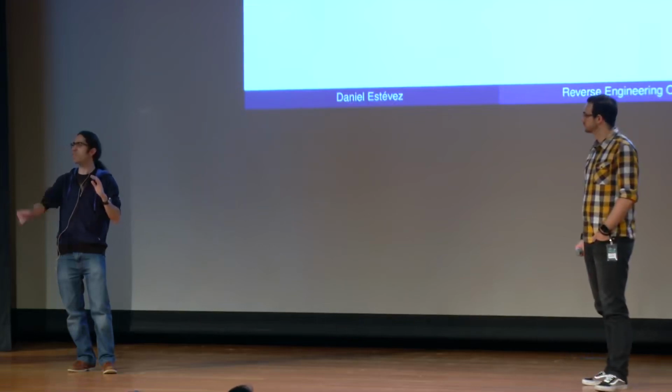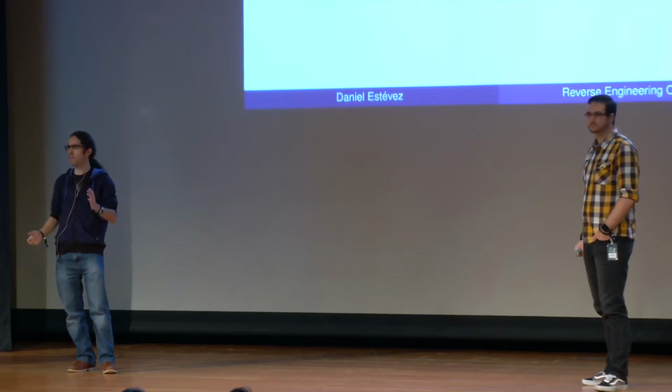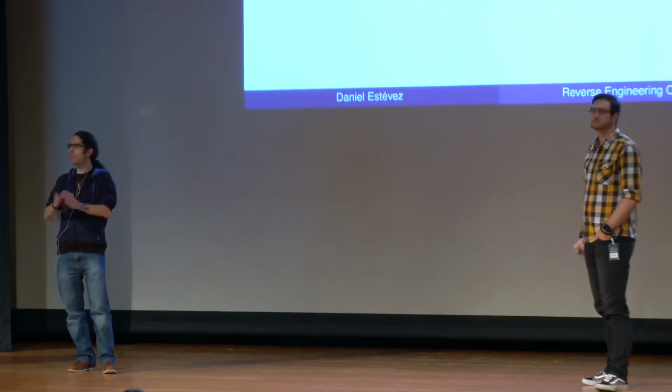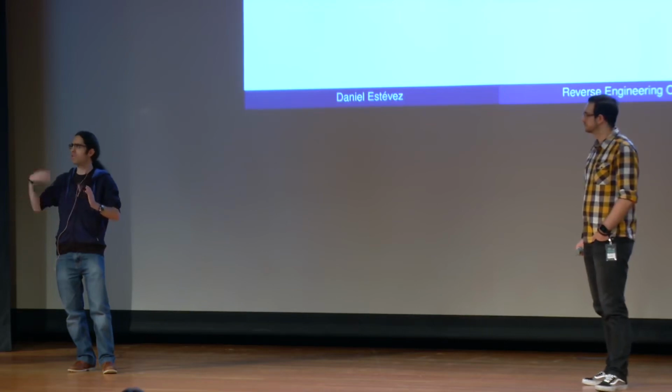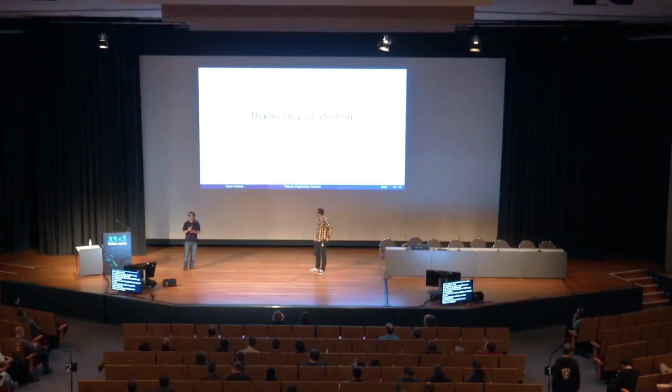For instance, in here, every time we have the Ethernet header, we have this whole bunch of FFF data, which is the broadcast MAC. So anytime you have patterns in your bit stream, if you modulate with any sort of modulation, be it BPSK or anything else, that means some pattern in the frequency domain. So that's not very good from the performance point of view of RF engineering. You get less performance with respect to signal-to-noise performance, also interference to other channels.